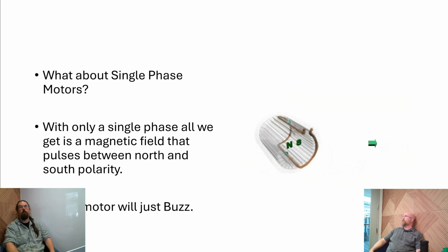Yeah, thinking back to the fundamentals of induction, and this concept of a changing magnetic field. If suddenly we no longer have something acting as a resistive element in that, the amount of current that will flow through a conductor in the presence of no resistance is infinity. And so you will literally melt the windings of a motor, just by holding it and standing it still.